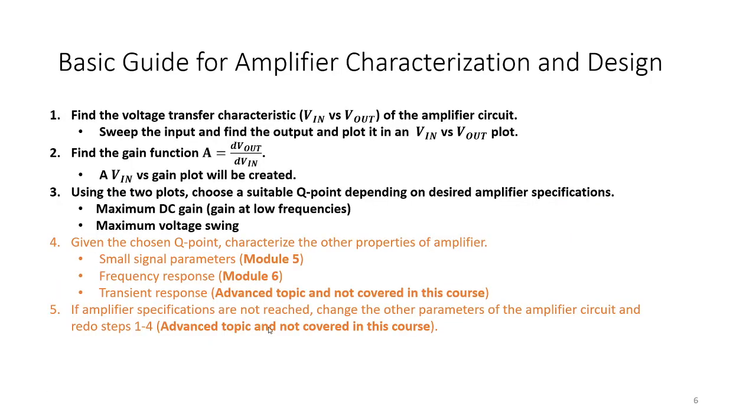What will be the guide for amplifier characterization and design? How do we characterize and how do we design amplifiers? A simple method is to use these steps. The first step, usually, if we have an amplifier on hand, is we find the voltage transfer characteristic, let's just call it VTC. That is V in versus V out of the amplifier circuit. How do we do this? We just sweep the input, find the output, and plot it in a V in versus V out plot. As you can see, these are all capital.